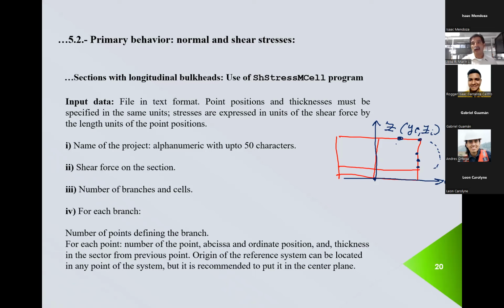In the case of the horizontal elements, for example, deck or double bottom, 2 elements is adequate, but usually I tend to use 1 intermediate in order to see the variation, okay? So that's that. What information do we need to include in this data file?